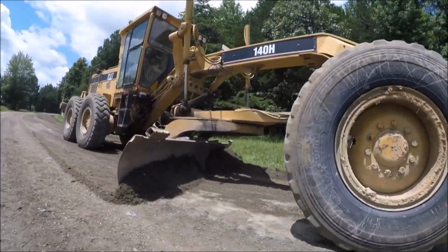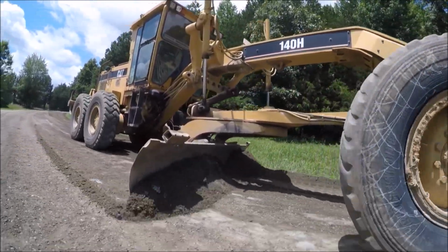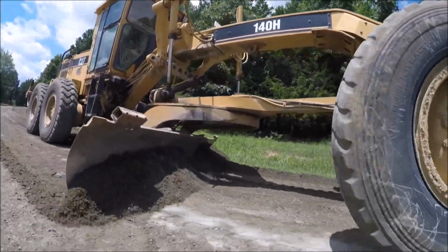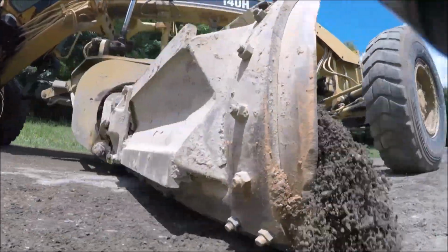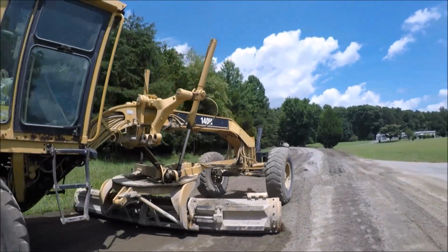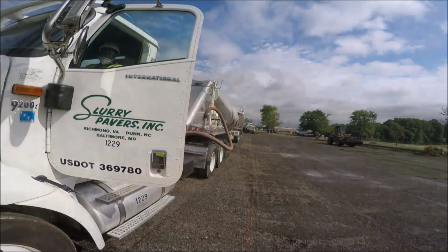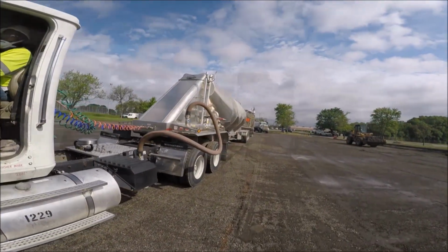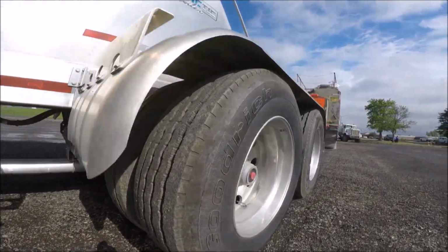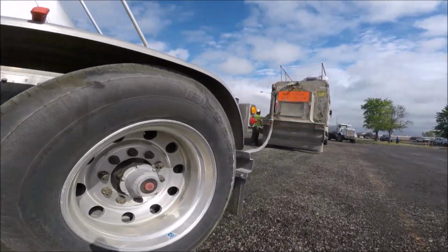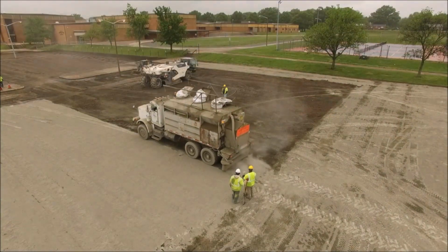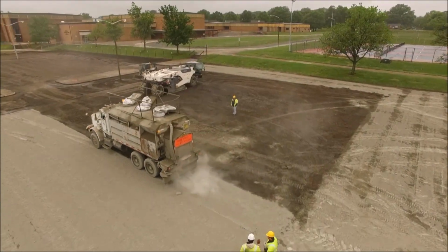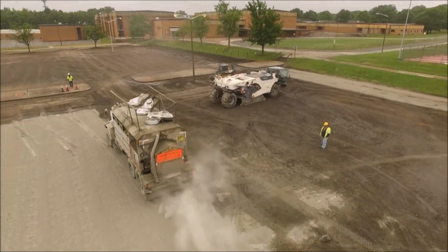So they've pulverized the roadway. You're changing the cross slopes, putting in a super, taking out some of the bird baths, maybe even widening the road a slight bit. Once you've done the rough grade, you're going to introduce the Portland cement. Here it comes in bulk tankers. It's pumped onto spreader trucks. It's delivered at whatever the required rate may be, 40, 50, 60 pounds.